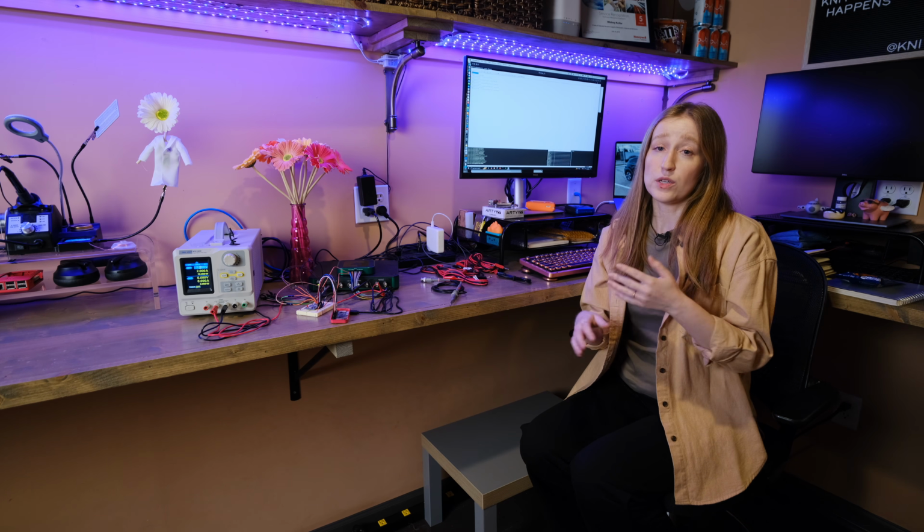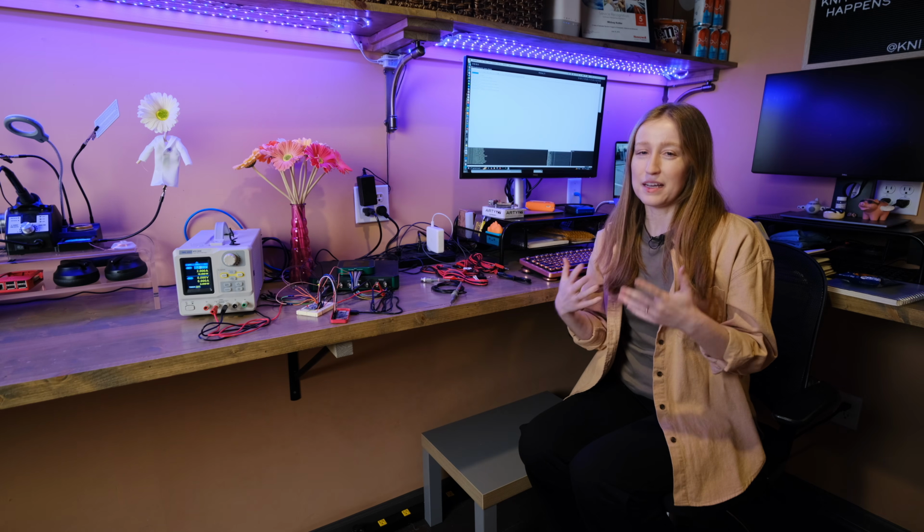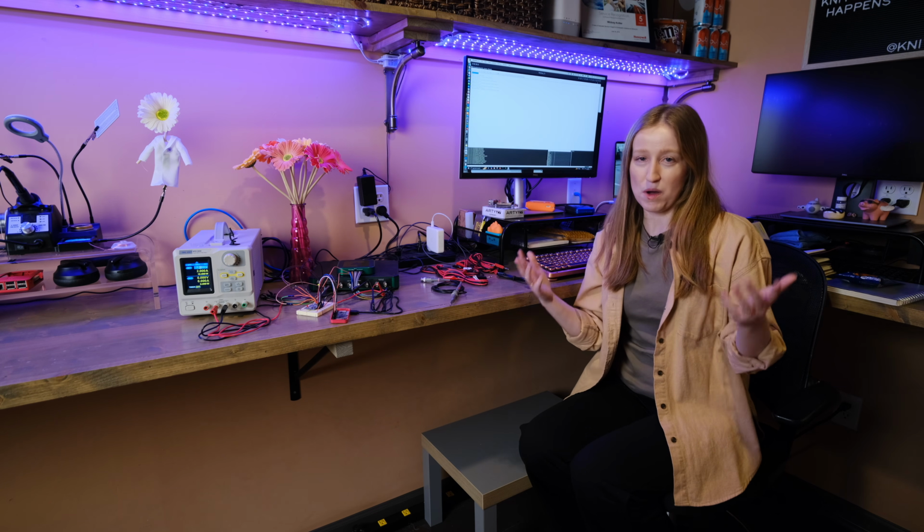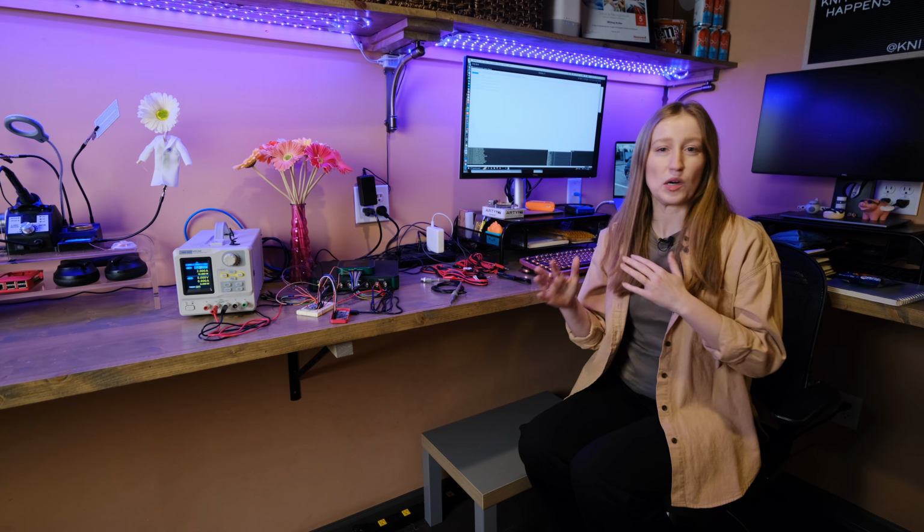And then also, one of the telltale signs that things are about to go off the rails in a setup is your current might get wonky. So always reading the current of your setup and how much your target device is drawing is a big thing that I always recommend, not only in remotely controlled setups, but in setups in general.